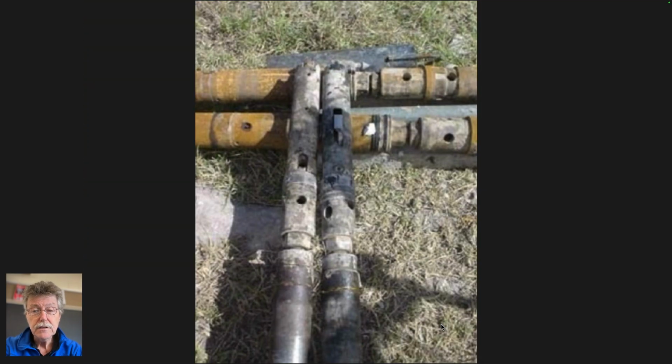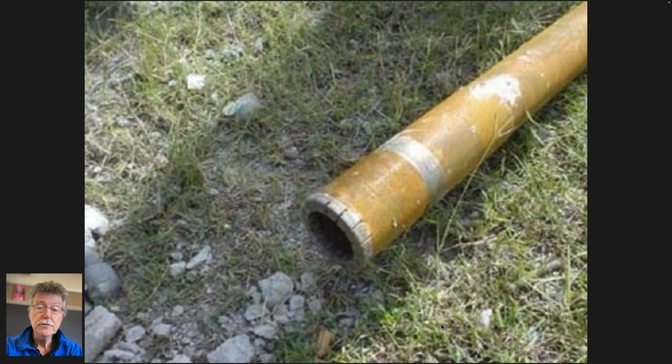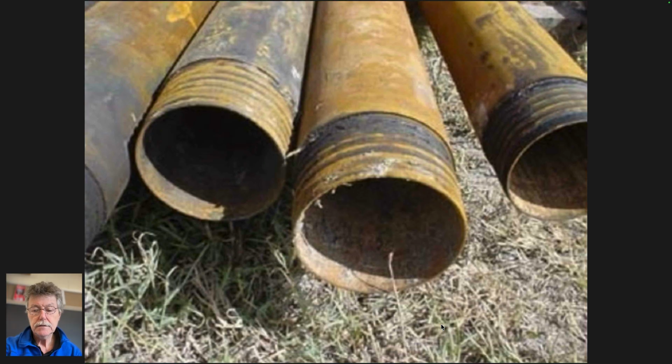I'm moving ahead and not telling you, but we mentioned the idea that what you'd like to do, once you're down at 200 meters, is not pull 20 10-meter pieces of pipe. They wouldn't be 10 meters, too tall to get in the mast. So once you're down with 15 pieces of connected rod in, you don't want to take those 15 out to be able to get a sample down the bottom and then put them back to advance to the next place again. So what you can use is a wire line.